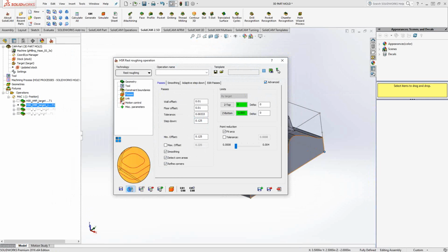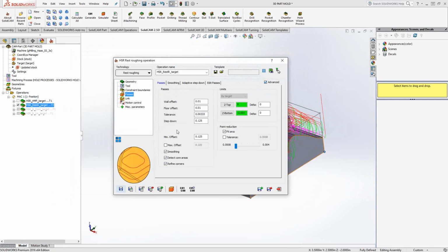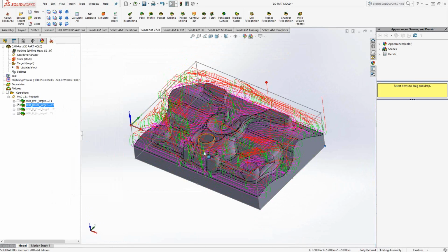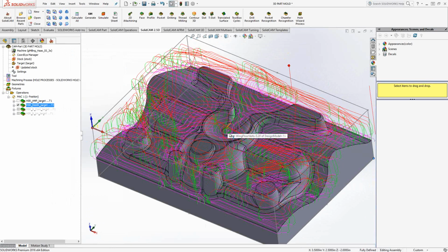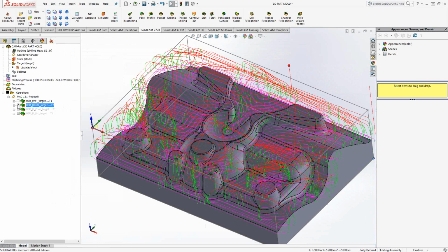And once I do the save and calculate, it's going to analyze the updated stock. So it knows that the previous tool removed everything with the 1/2 inch end mill. So what is remaining, it will be only attacked by the 1/4 inch. Once we get back to that, you'll see that the material that was left over in some of these deeper areas, that's what the 1/4 inch was able to do. Okay. So just similar to other 3D toolpaths, rest roughing is just a remaining stock toolpath.